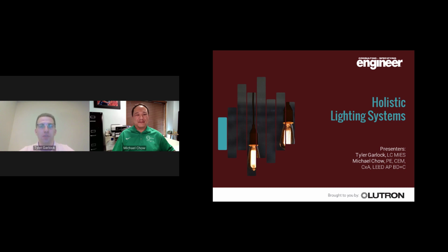So for those of you that aren't familiar, and I know Michael mentioned this earlier, CRI, which stands for Color Rendering Index, is a set of colors. It was originally 1 through 8, and now there are, I think, 13 or something like that. I don't have the exact number in front of me, I'm sorry. Each one of those numbers, R1, R2, R3, R4, R5, R6, R7, R8, is a specific color, and there is a control color which is tested against the color produced from a light source. That control color is what it's supposed to look like under sunlight.